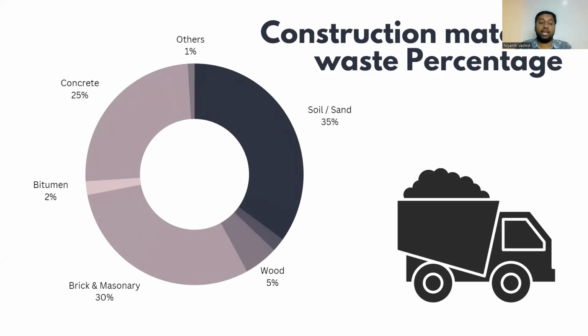Next, we get into brick and masonry. If it is a sand or soil brick or clay brick, it makes sense. But if it is a concrete block, then it's a problem. Because if it's a clay brick, you can just dispose of it and demolish the whole block and it will just be soil at the end of the day. But if it is a concrete block or an AAC block, then it's an issue when you dispose of it.